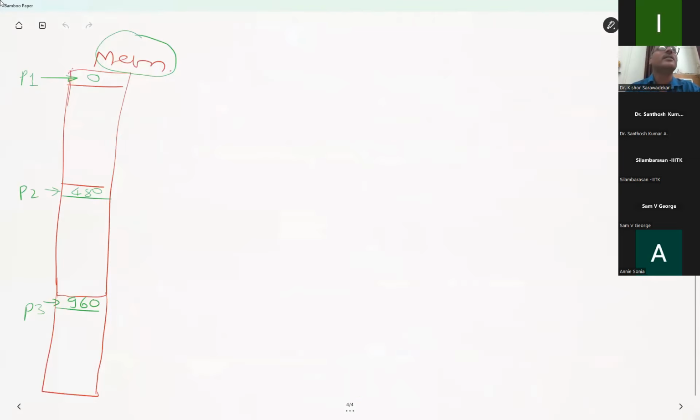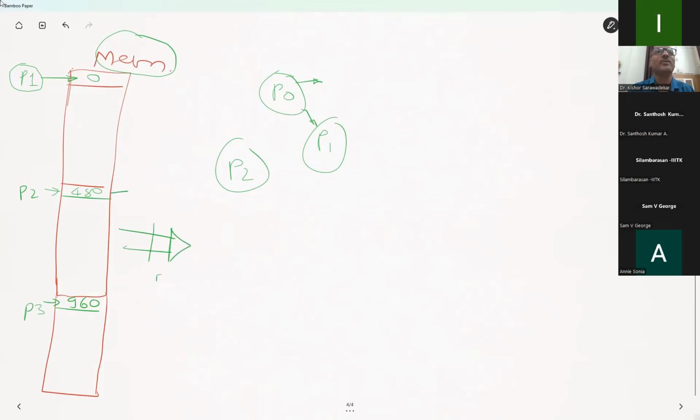Okay. So on reset, when count is equal to 0, this is already there. Then we can have one more state machine designed which will keep on saying P0, P1, P2. You generate the address and read the data. Then this will give the call to P1 so that you will reach here, generate the data, and send it at the output here, the memory out.